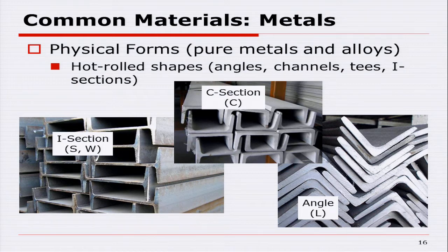And your bending moment changes as you go along the member, so you'd want your depth to change as you go along the member. Well, these things have a fixed depth, so it's not efficient to typically use those types of sections. You want to have something specially made. And for our lower rise steel frame buildings, that's what we do. We make our I sections, but we weld 3 pieces together to do that.